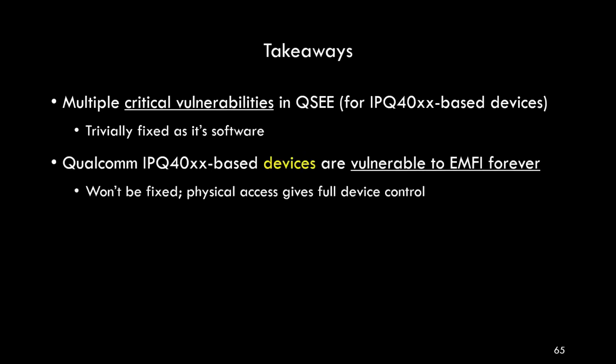We also identified that the Qualcomm IPQ40XX-based devices, and more specifically the chips that are used to make those devices, are vulnerable to EMFI forever. Qualcomm simply indicated to us that this vulnerability will not be fixed, as it is not considered a threat for the threat model that they came up with for these particular chips.